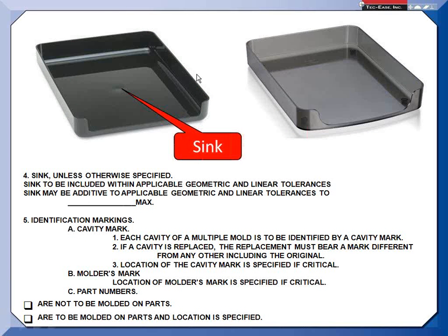And by the way, I've got this letter tray, you know, those in-out baskets, and I just want to mention something. I was visiting a friend. He was a manufacturing engineer at a company that made molded parts, and they made this sort of stuff, and then they chrome plated it. Well, he showed me a brochure. He didn't even show me the real part. He showed me a brochure that had a chrome plated plastic letter tray like this, and the ejector pin marks were right up here on the top. Instead of putting them on the bottom where nobody'd see them, nothing was said on the drawing, so all around here you had ejector pin marks.